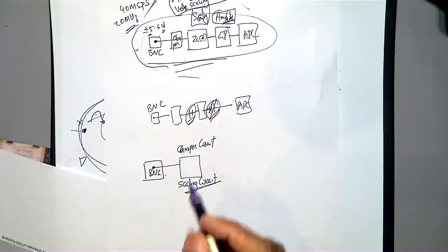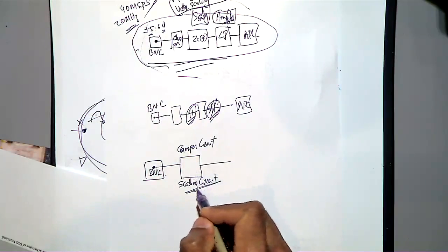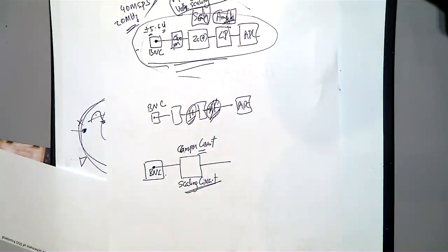After that, usually what we do is, this is a scaling circuit or clamper circuit. Then after this scaling circuit, you got the BNC, and most of the time when you design the system, it is good to have a buffer circuit. The advantage of a buffer circuit is that it isolates whatever you connect from what is going in. When you connect something external, you want to make sure the impedance values are not much affecting what comes after that. So they connect a buffer circuit.